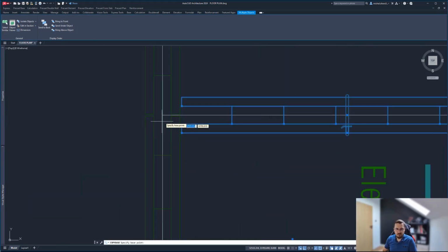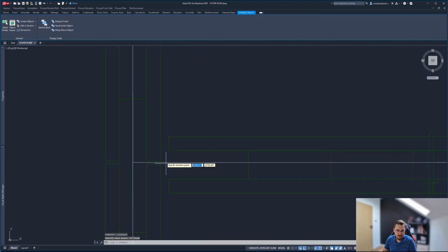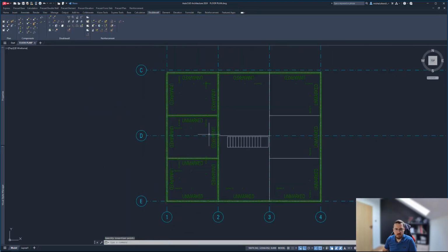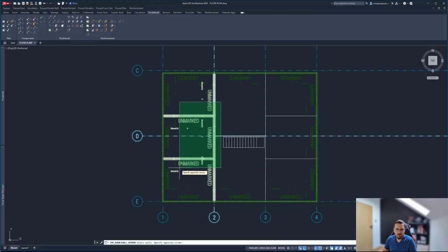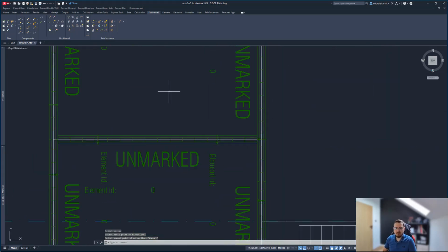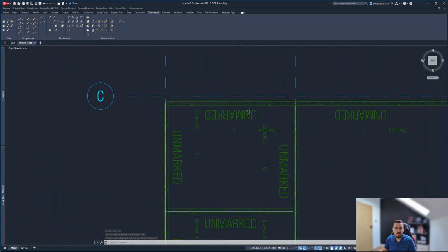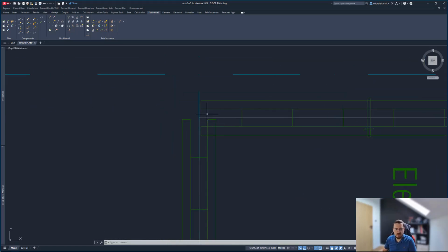And with that, I can also copy the walls with standard AutoCAD commands, so I don't have to draft everything manually. And I can also use a mirror tool, so I can copy those walls to the other side, right? But maybe before I copy those, let's focus on actually editing those walls slightly. So what I mean by that, for example, here, that's the start point and my end point of the whole placement of the external double walls.